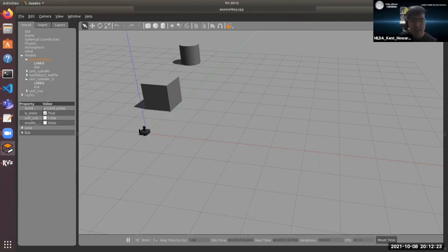So we start, in my case, I think I started with minus 3.14. So the error angle will be this angle here. This is 0. This is the error angle. And I'll use this as the error in my PID controller and multiply the error by the kp, and then multiply its derivative by kd, and multiply its sum by ki. And that output is the velocity twist message angular z value, which will in turn turn the robot.